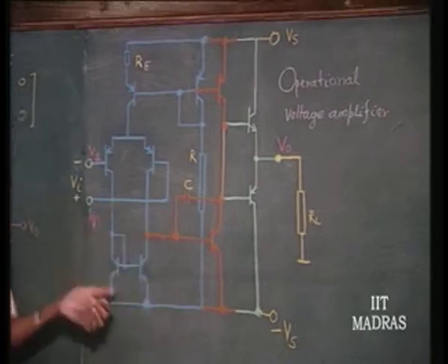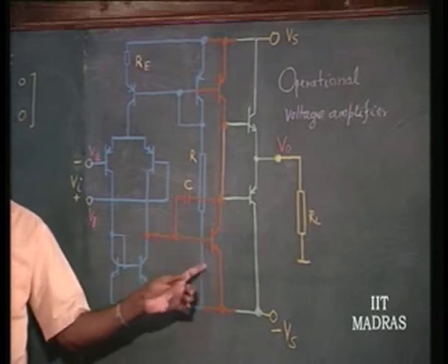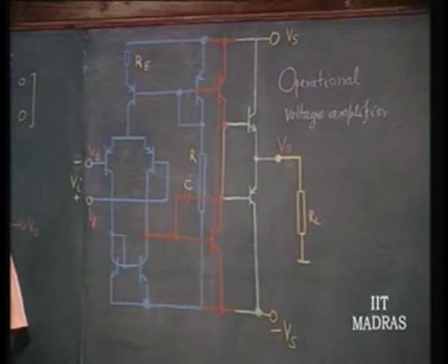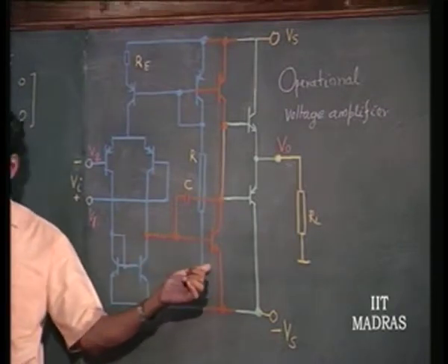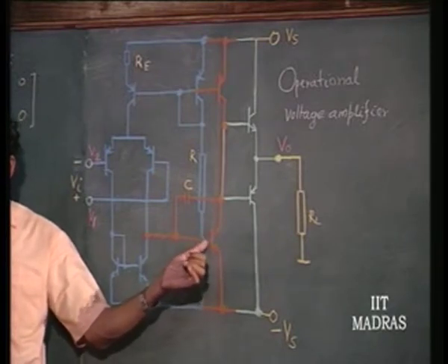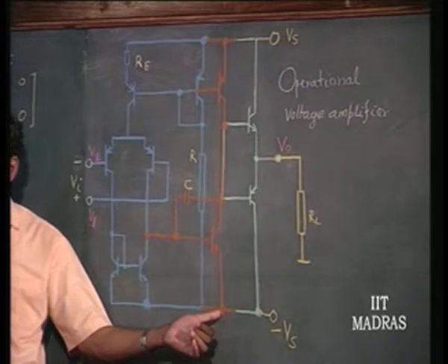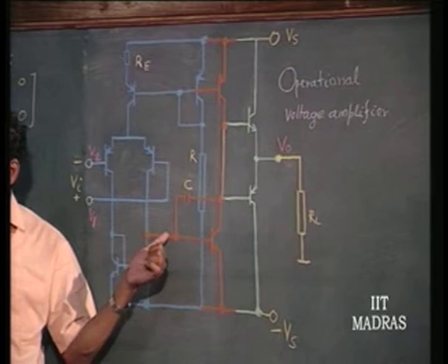Do you now understand why this configuration has been chosen? Okay? That is, the intermediate stage has got to be the high gain stage. Okay. The good NPN transistor will necessarily have high gain and good speed of operation, high frequency. So, this particular thing is going to have very high gain. That means, it is a common emitter stage here. Emitter is AC bias grounded, that means it is connected to the most negative potential for biasing purposes, and then from here you have one diode drop higher.